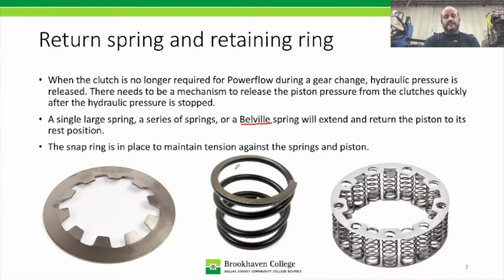So the next style is just a big single coil spring. And it's pretty simple. This top part is going to be retained by a snap ring. The bottom part is pushing down against the piston. And when the piston is applied, it's going to compress the spring.